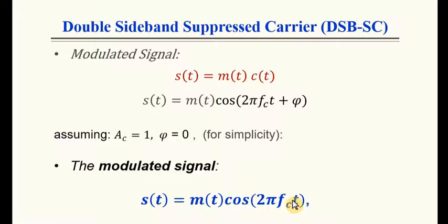We also know that, unlike AM modulation, double sideband suppressed carrier modulation is reduced to zero whenever the message signal is switched off. If we switch off the message signal, then s(t) will become equal to 0. Most noticeably, however, the modulated signal s(t) undergoes phase reversal whenever the message signal crosses the 0, as we will see later, inshallah.